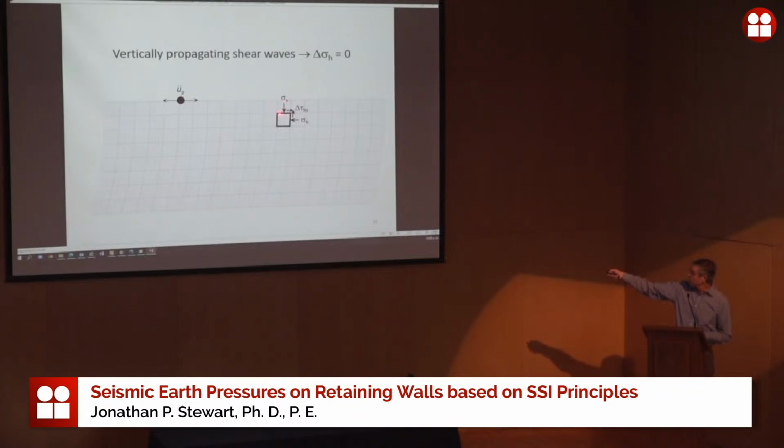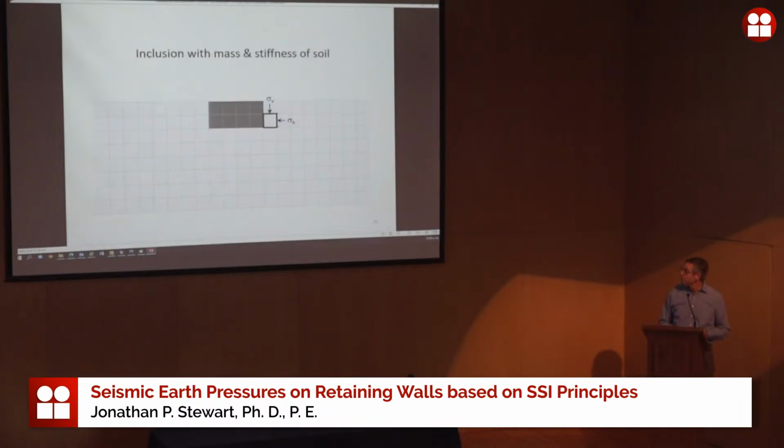So the inertia of what is above that element is accommodated by the development of this shear stress, which is the same on the horizontal and vertical planes. That's important. The inertia is actually completely handled by the change in shear. There is no change in the vertical stress, and there is no change in the horizontal stress. Of course, I'm not considering liquefaction and those kind of things that would change effective stresses. If we leave that aside, say there's no pore pressure development, everything is handled here in the form of the shear stress.